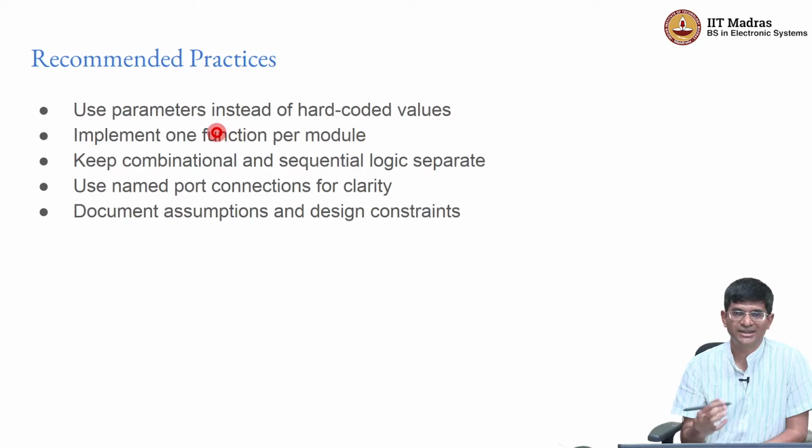But once again, that ALU, right, the arithmetic and logic unit, has pretty much only a restricted set of functionality. It takes certain inputs, it takes a opcode, performs a computation and gives you an output, right? So by having that kind of limited functionality associated with each module and then composing those together, it makes your hardware much easier to design and to debug.